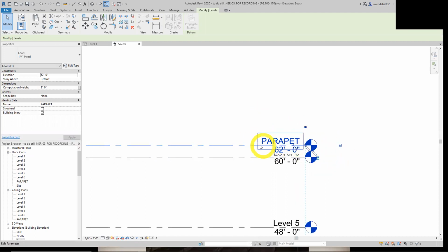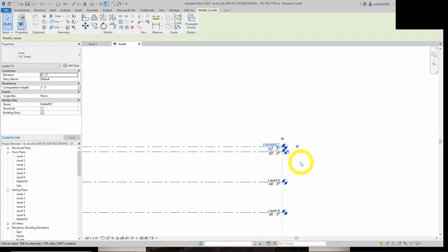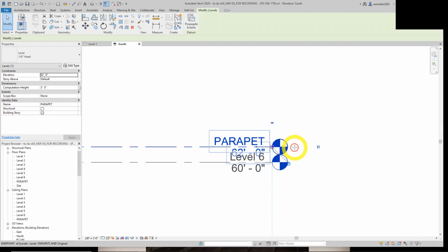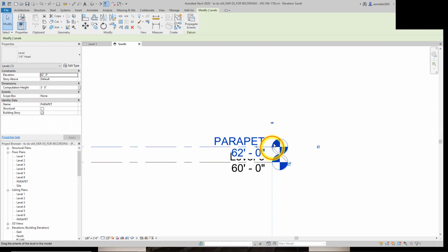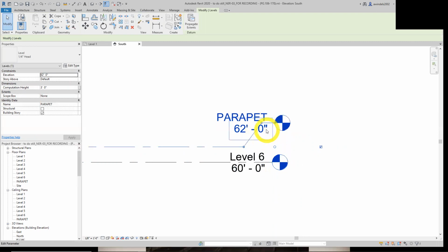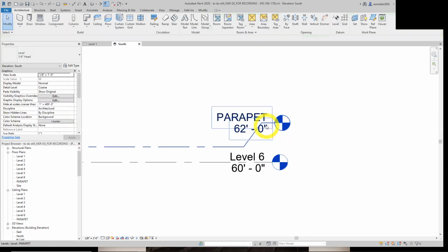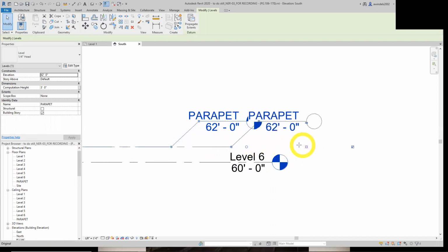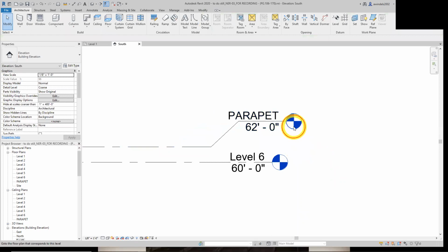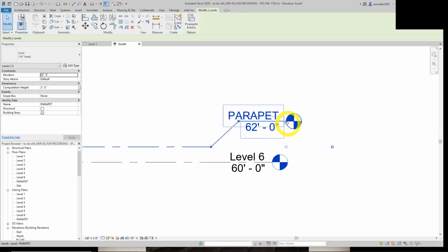Bear with me a second. I'm in trouble getting it to grip the way I want. Let's try by unlocking it again. There we go. That was the button I was looking for. The middle break button there. So we go back. It's going to go out like so. I accidentally changed the height. Let's go back to 62 feet. Slide these grips. So escape twice, provided it's unlocked, and it was.